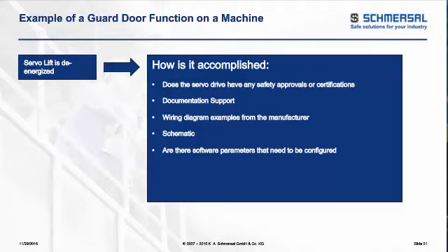Unfortunately, a lot of times people are breaking just the enabling signal because they don't want to remove the power to the drive. That's not always the safe way of doing it, to ensure that servo or that AC motor doesn't randomly take off because a sensor got hit or a switch got bumped and all of a sudden motion takes place. You're not protecting people from being seriously hurt.